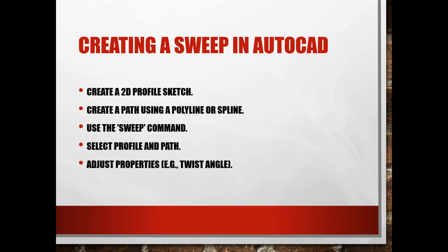All right. When we're getting to the sweep command in AutoCAD, we're going to first create that profile, right? And remember that in AutoCAD, it's got to be super exact. So whatever you create, you're going to be creating those dimensions right off the bat. You're going to put them all together. And you've got to create them also on one plane. That is the next thing that you really need to know, that it needs to be on one plane. It needs to be on whatever flat surface it is. Otherwise, the join won't let you work. Remember, join is a 2D command,